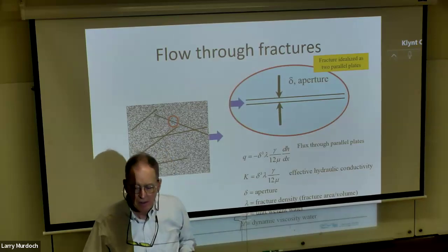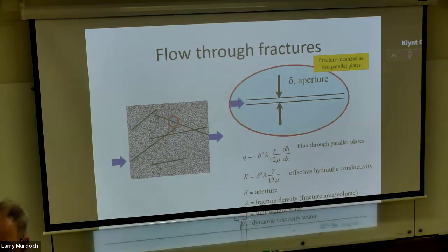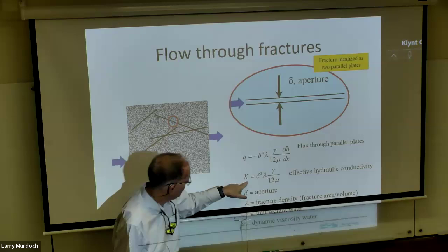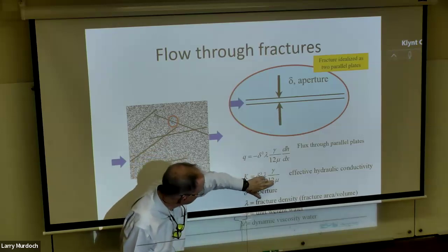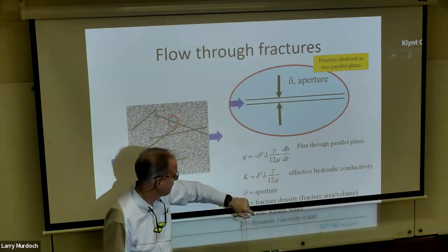So remember, what's the difference between the hydraulic conductivity and permeability? Hydraulic conductivity is dependent on the porous media and the fluid, and then the other one's dependent just on the porous media. Cool, great. So these are the two fluid properties, unit weight and viscosity.